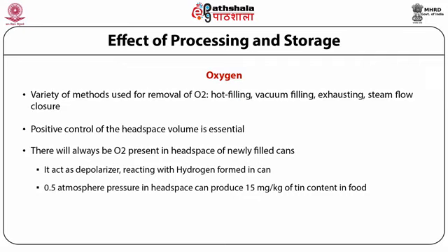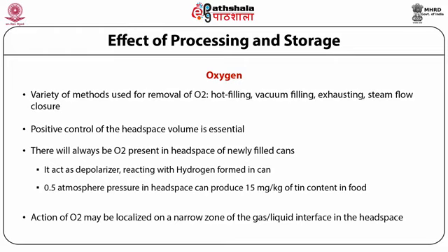Although this is a relatively small amount in comparison with the total coating weight, the action of the oxygen may be localized on a narrow zone of the gas or liquid interface in the headspace. This may result in the production of an unsightly tide line, even exposure of an area of steel much larger than that exposed at pores in the initial coating.